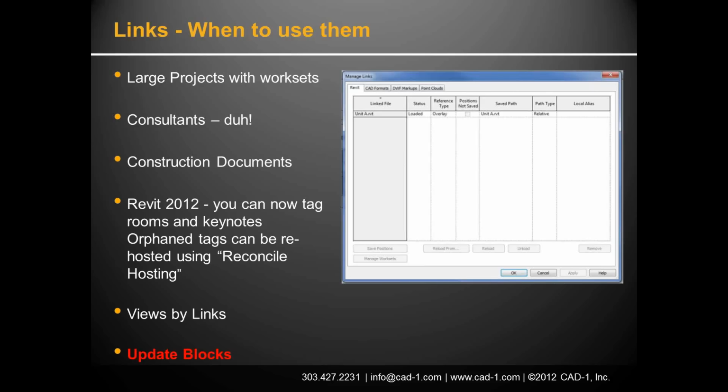All right. So next we'll talk about links, large projects with work sets. It's a great time to be using links to develop those. I put in there consultants, like a no-duh. Yeah, we know you're bringing in structure. It's going to be brought in as a link. But I just want to throw it out there to get people understanding. Yeah, those are links. They're also going to be work sets too, so your consultant stuff's going to be out there. When you move into construction document phase, going from your schematic, your DD, getting into the CDs,